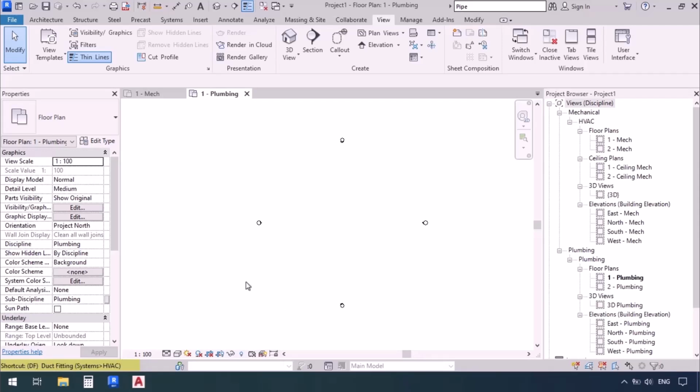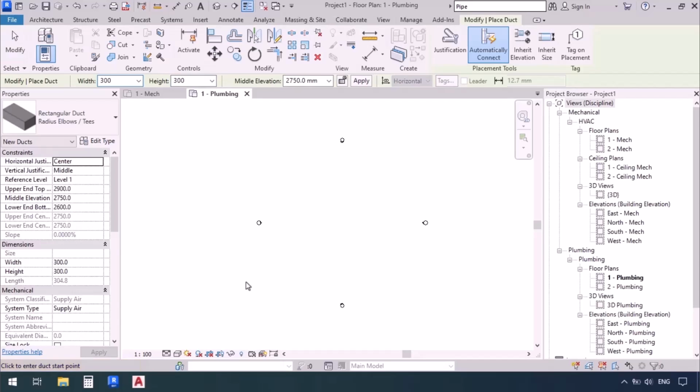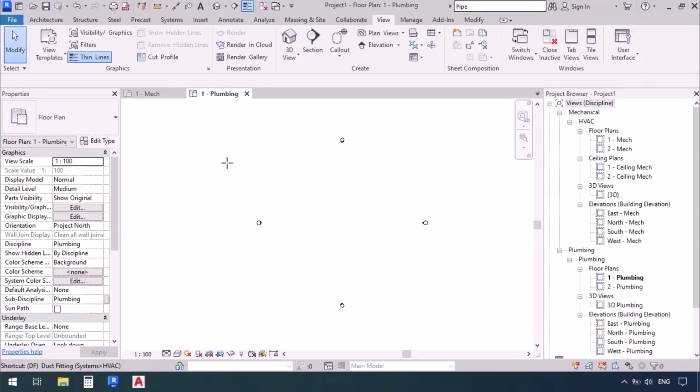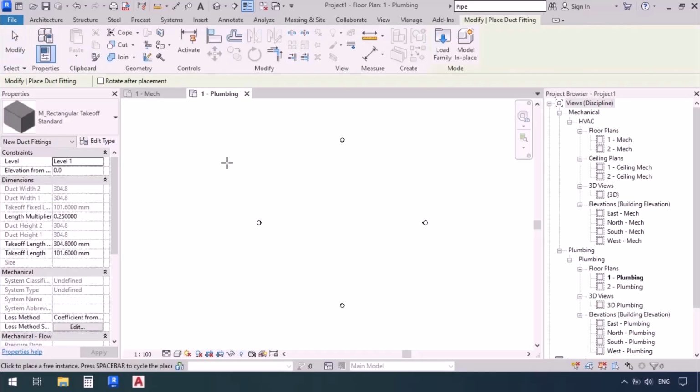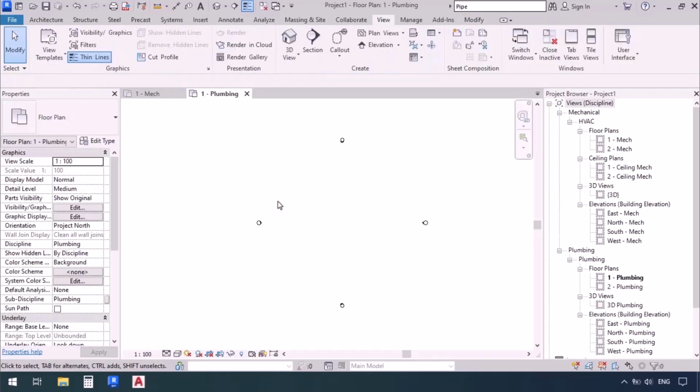And as you can see, they can change because I am currently pressing on the up and down arrow keys on keyboard. And as I do that, the command would switch from duct and duct fitting. Now it's on duct, so I'm going to press enter. As you can see, it shows me the duct command. So again, let's press DF, and then the duct fitting command would be selected. Okay, so you can have the same shortcut for different things, but it's best that you don't.